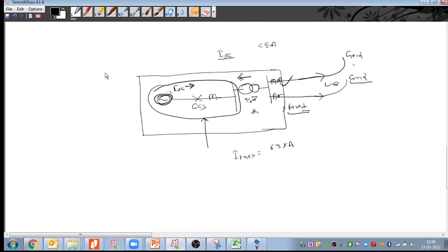Basically, from my experience, you calculate the generator, because for the generators you are taking 63 kA, which is from CA, but the generator itself depends on how much it contributes. If you have one generator or two or three generators, we personally usually use the available fault current from the generator, or whichever is the maximum. Just compare it and then use this one.